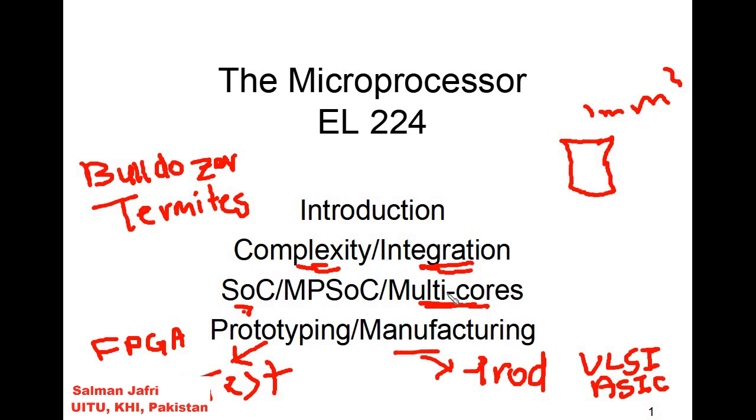Having multiple cores and operating those cores at lower frequency can help us bring down the power consumption. So the power of your circuit can be reduced by operating multiple physical cores at lower frequencies. For example, if we have a quad core processor consisting of 4 cores, then the 4 cores can be operated at half the frequency, or just 500 megahertz.